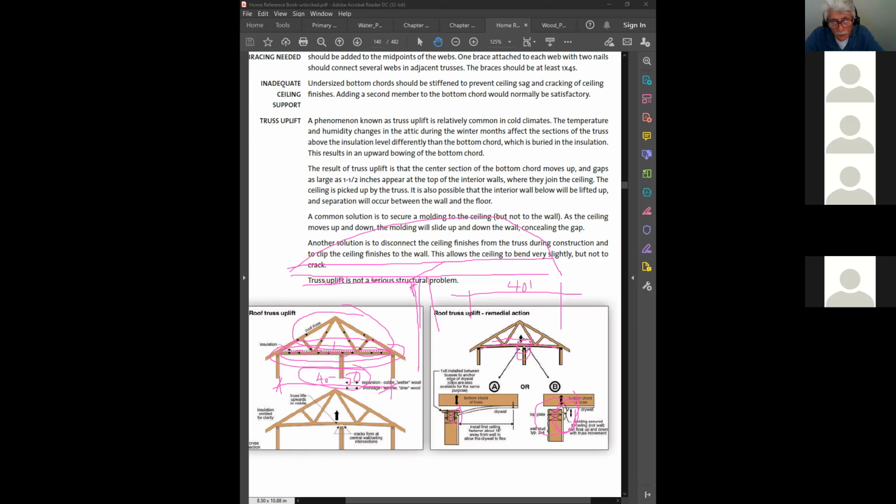Do you understand? Now, you want to see another problem with wood construction that people don't have? So this is a typical, like I said, the spans have to be 40, 50 feet. I personally don't think I've ever seen this with trusses that are 30 feet in span. And most houses have 30 feet spans, because they'll always try to span the trusses in the short direction of the exterior walls. So that's why this doesn't become an issue.